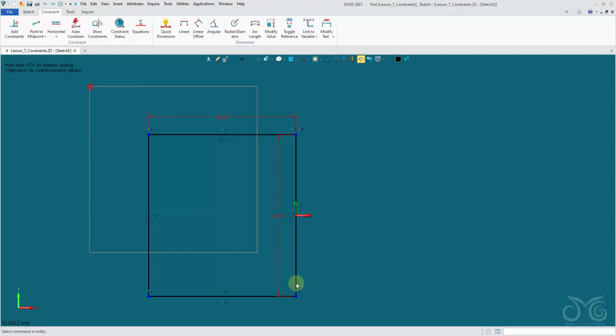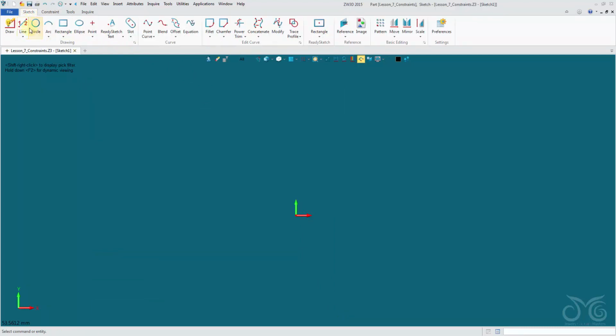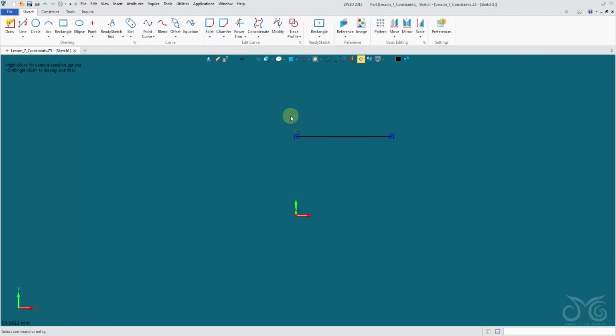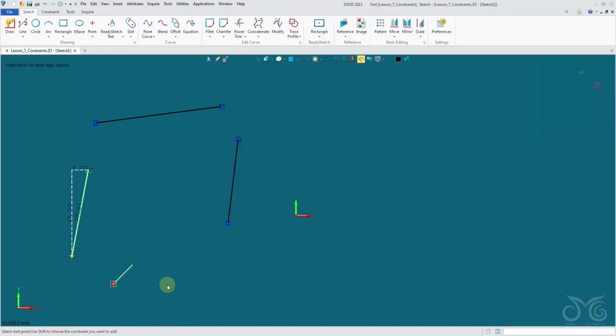So I'm going to delete this, and I'm going to redraw some of our lines. Okay, so we've seen before our smart picking snaps. They'll throw in auto constraints, okay, and this can help us constrain our geometry faster. Okay, also, let me just erase this and draw our 4 2-point lines again. Okay, I'll take out this constraint.